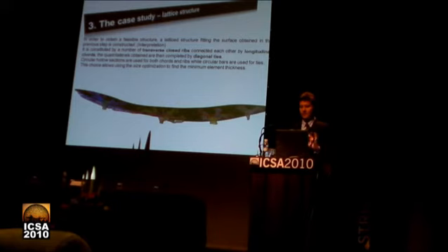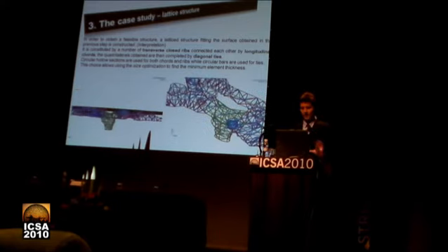So we create the structure to imitate the shape in this way, and then create a database with different cross-sections. We put these different cross-sections in the software and run a size optimization. So we have exactly the number of pieces and the section of the pieces to have the lightest structure in total respect of the stress limits of the standard. And to have a small number of sections, we create a small database, of course.